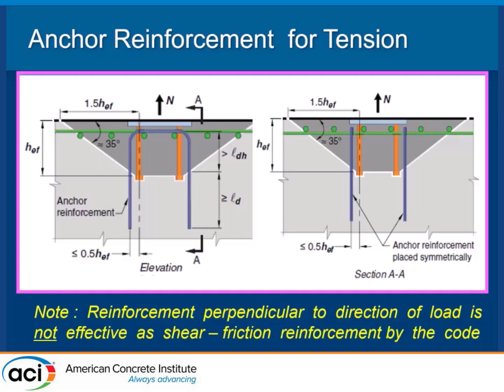I don't have to design it. There's no size, there's no nothing. And you get about a 10 to 15% boost in your values. So if you're designing in the top of a pier, which we'll talk about a little later, and I've already got vertical reinforcement, my longitudinal reinforcement in my column or pier, and I can put my anchors in, it's there. I don't have to even use it, but I can call it supplementary reinforcement, and I get a 15% boost in a concrete breakout calculation.